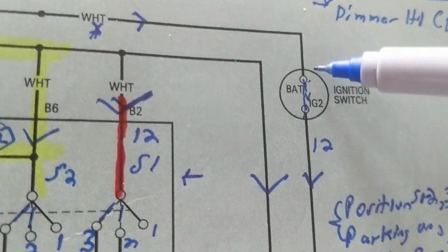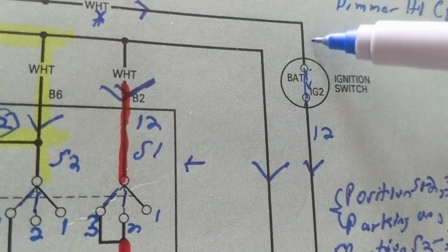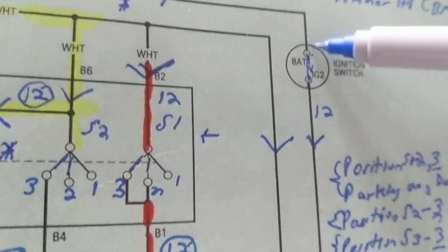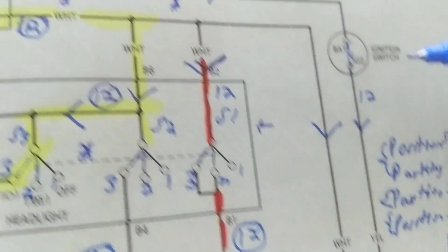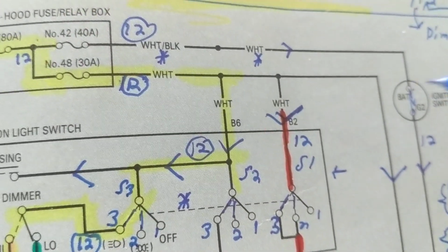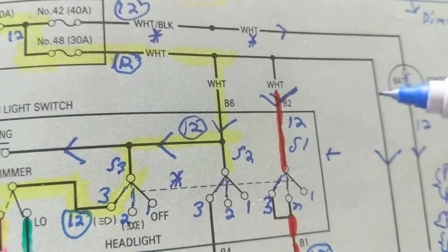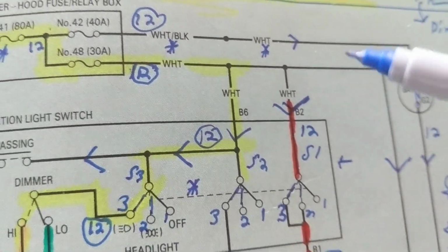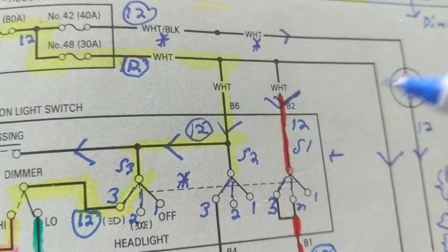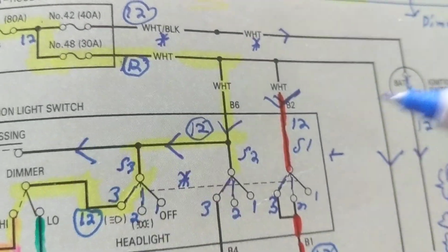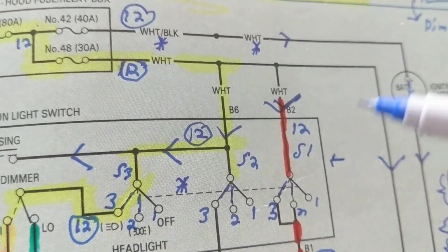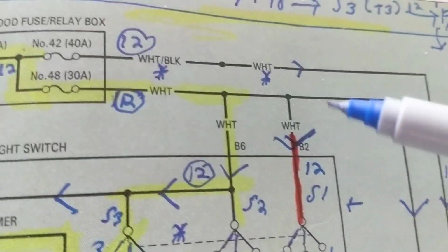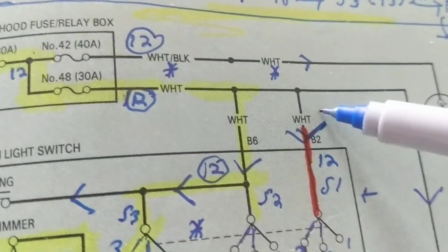The ignition switch, obviously, in battery, and when we crank it, IG2, we're closing the circuit. Remember, we need a closed path for current to flow, and I always teach current, not voltage. Voltage is present in a battery, whether it's connected or not. The outlet in your home has 120 volts. If you do not connect any appliance to that outlet, you still measure 120 volts. Are you pulling current if you have no appliance? You're not.